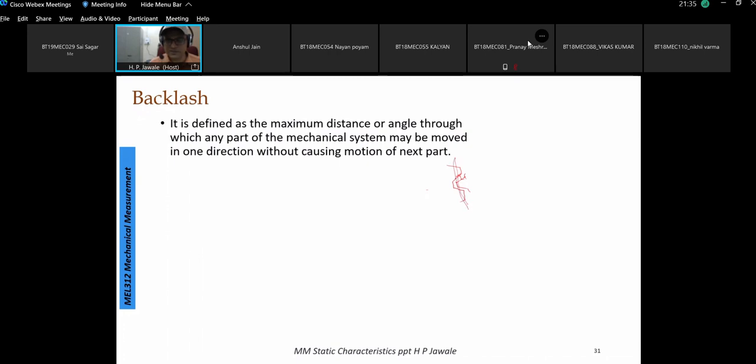You find there is a difference between the shapes. So it means that unless this deformation del is covered, no further motion, no contact between teeth 1 and teeth 2 is going to occur. It also means that teeth 2 will not start any movement till this slackness or this gap is bridged.